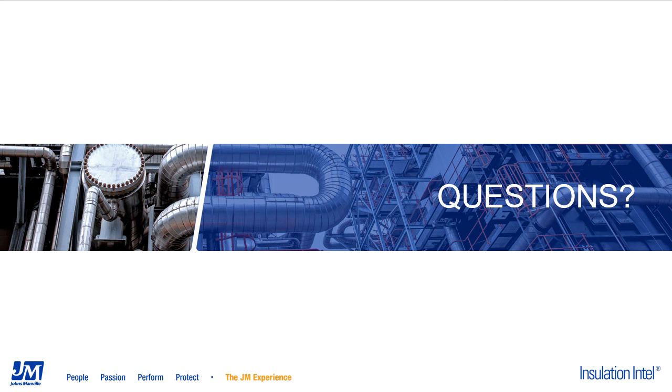I can add a tiny bit to that, Jim. I suspect that the questioner is inquiring about infrared thermography. And in that regard, what you're going to find is that the low emittance metal jacketing does not lend itself well to infrared thermography because it is highly reflective of infrared energy. So if you try to do infrared thermography with metal jacketing, you're going to get a nice reading of the temperature of the metal, but not a good indication of what's going on beneath the metal.